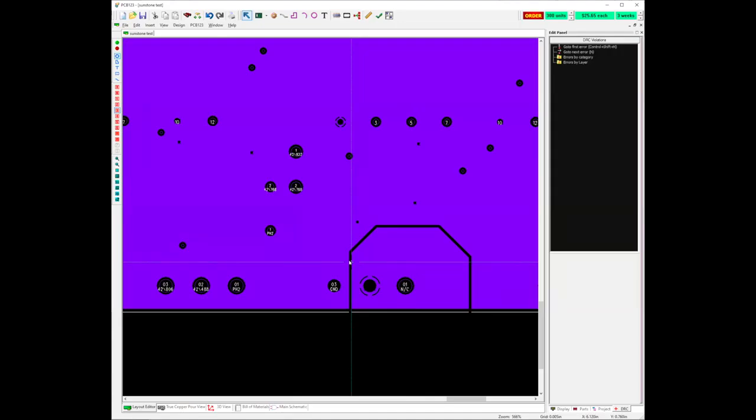And this can happen with voltages. You want to separate half of your board and have it plus 5 volts and the other half of your board 12 volts. Okay, great. You can do this and add the plane layer and split it and keep track of that manually and trust yourself. Or